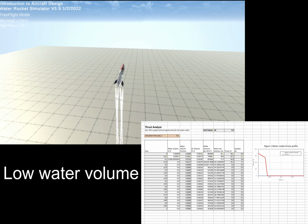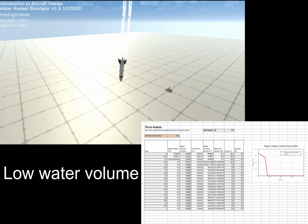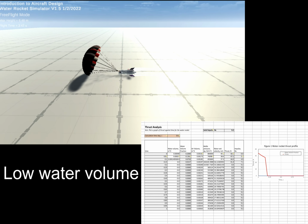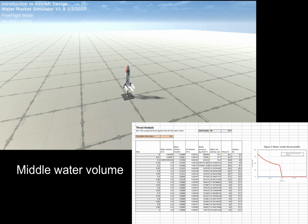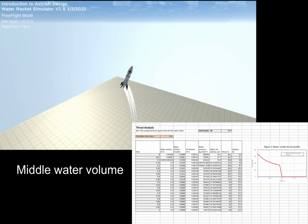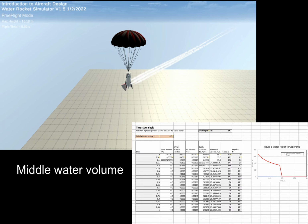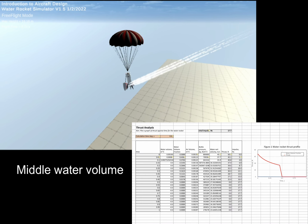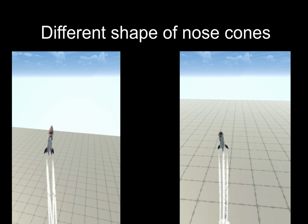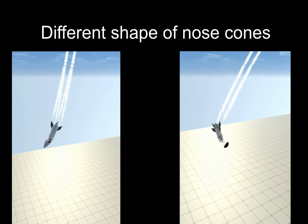The lower the weight of the rocket, the better it will fly. The less weight it has, the more aerodynamically stable the rocket can be to produce a good flight trajectory. And a good flight trajectory needs to be maintained because the rocket needs to land in the designated area. Having a center of mass forward will keep it more stable. This is where the fin position and the size has to be considered in order for the best position of center of mass. The nose cone will be required to be as streamlined as possible because this feature will cut through the air first, and the nose cone will also hold the parachute.